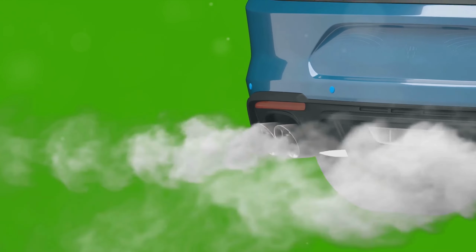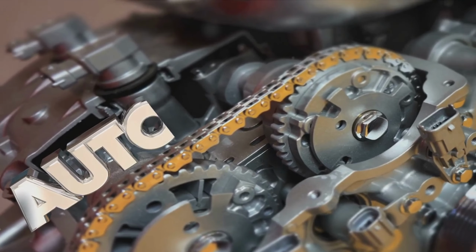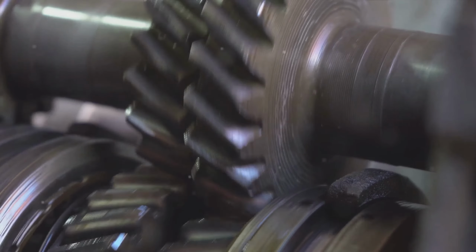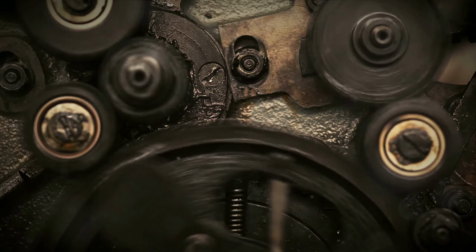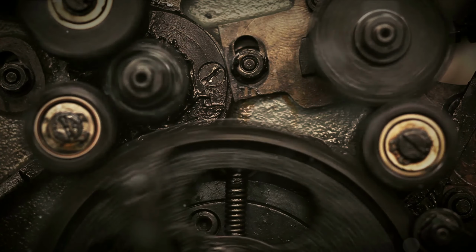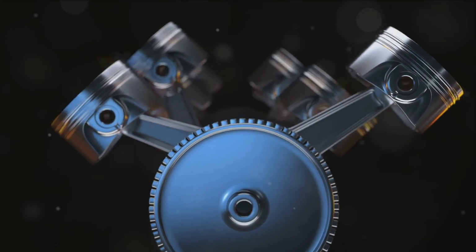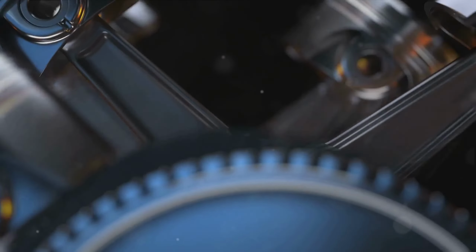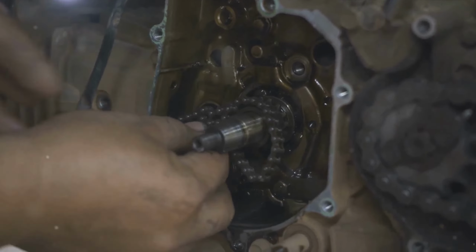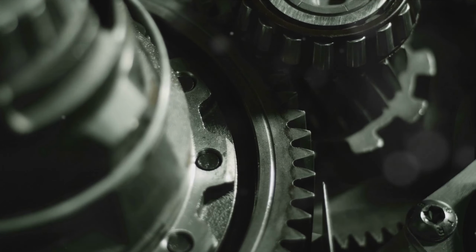On the other hand, the MRF model is used to simulate the effects of rotating machinery without the need for a dynamic mesh. This is important in scenarios where the rotation of components like wheels, gears, and turbines needs to be analyzed. Together, these models enable automotive engineers to accurately simulate and analyze the performance of various components and systems in vehicles, leading to better design and optimization.